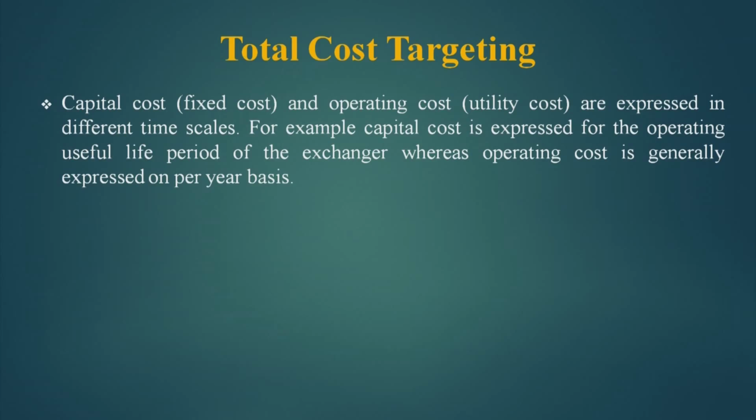The capital cost or fixed cost and operating cost, which is a utility cost, or a pumping cost, or a mix of these two, are expressed in different time scales. This is very important. The fixed cost is expressed for the full operating life of the heat exchanger, whereas the operating cost is expressed on a yearly basis. So, the time scales are different, and hence we cannot add them.